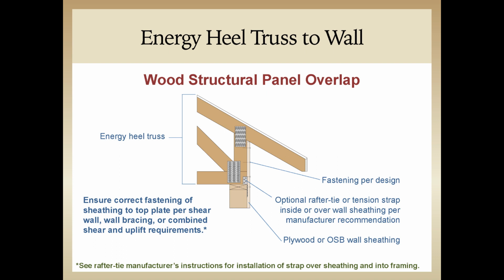A raised heel truss also provides a method of attaching the wall sheathing to the truss, which may provide uplift resistance and may help eliminate or reduce the need for additional metal hardware. And this should be verified by the designer of record.